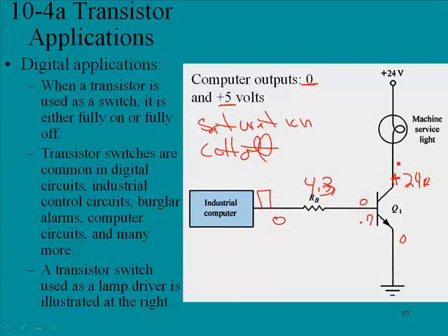also go into saturation. And usually what you'll see here, remember we've got 0 here, we see 0.7 here. Recall that this is just another diode here. Okay, this is just another diode, and it's going to saturate. It's going to conduct as hard as it can, and so if there's 0.7 here, then this is going to reach towards 0. Now what you'll usually see is maybe 0.1 to maybe 0.2 volts here.